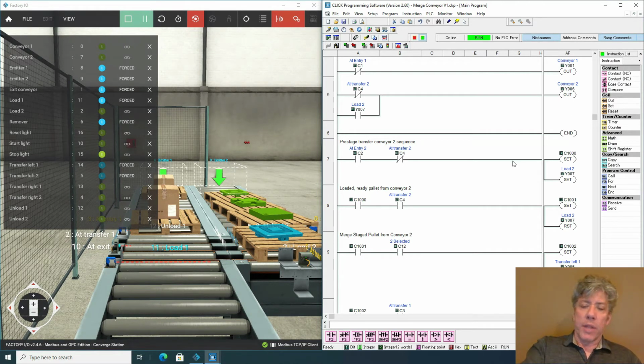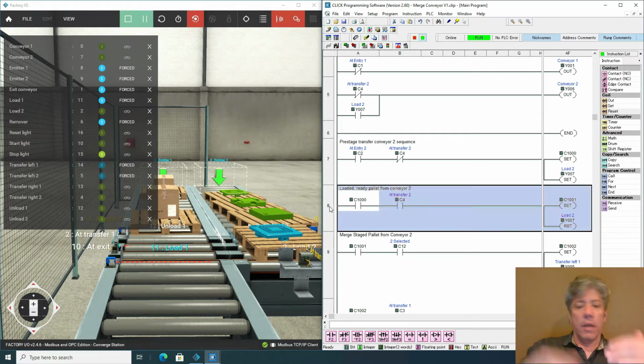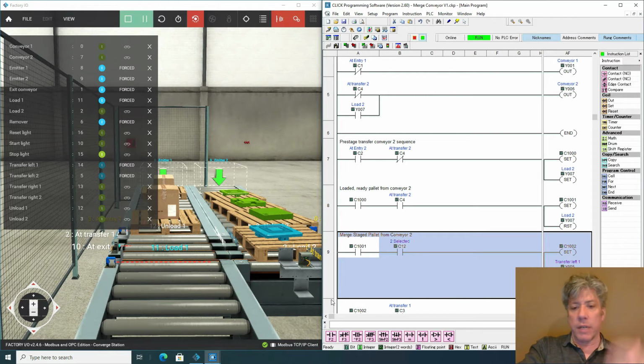And there's a problem with that because the order, the flow that is inherent in most programming languages is really not there in PLC programming. And so what I'm doing by adding all these bits is I'm forcing an order to occur, right? I'm saying, okay, an event happens, I want to remember that because I know I'm going to fly down quickly to rung 8, the PLC is going to evaluate it, it's going to evaluate 9, it's going to evaluate 10, and so on and so forth.